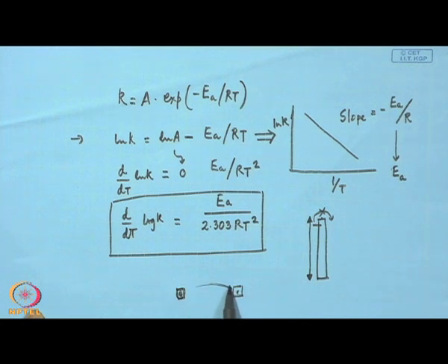So, in order to move the particle, you need to create a vacancy, a free space over here. To create that free space, you need to put in some amount of energy, and that amount of energy may be termed as the corresponding activation energy. That is, you need to activate it, similar to activation energy.